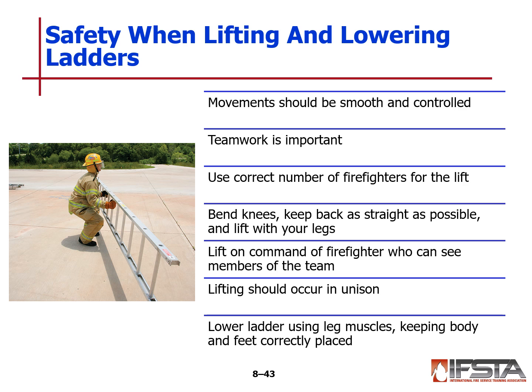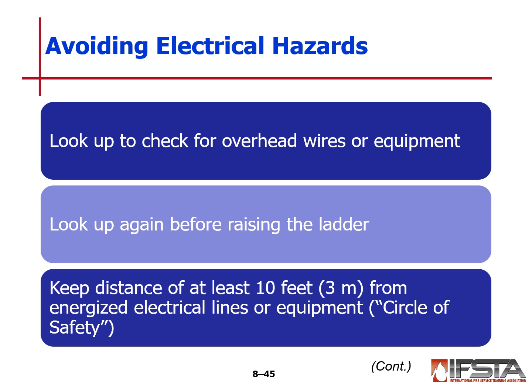When we lower the ladder, again, use your leg muscles, keep your back straight, and your feet correctly placed on the ground. I know this is in here several times, but avoid electrical hazards. Always look up to check for overhead wires and power drops or other equipment. Look up again before you raise that ladder. Keep your distance at least 10 feet from energized electrical lines or equipment.